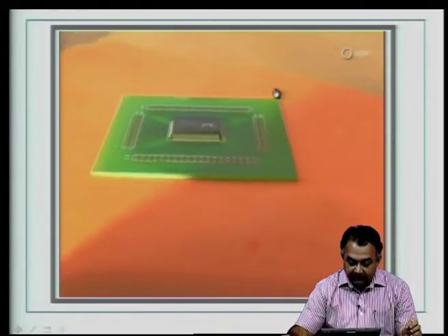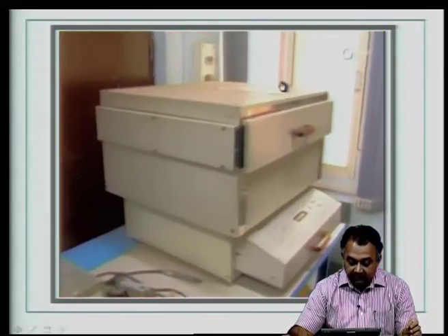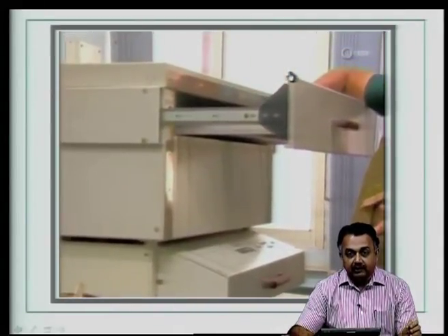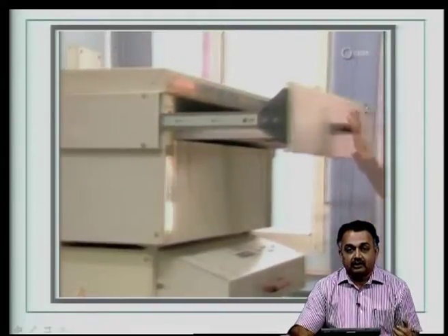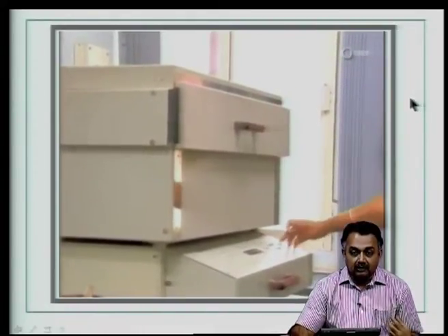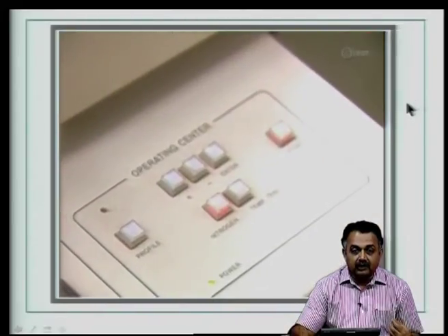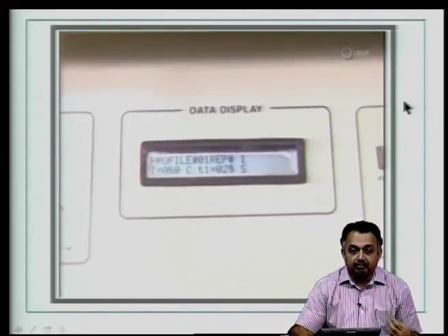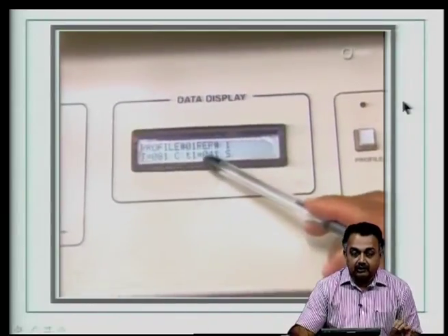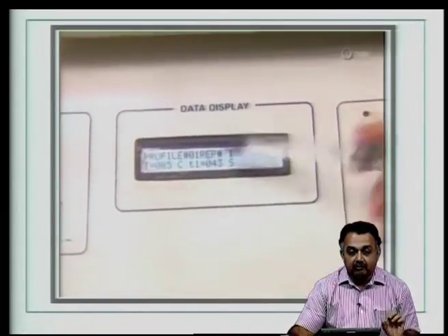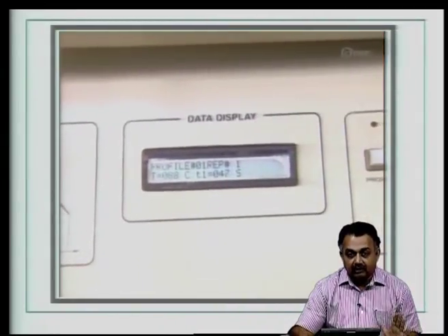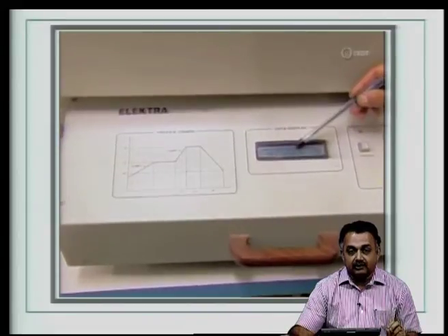So, once you are satisfied with the alignment process, again you take the board to the reflow, and then you expect due to surface tension the solder does not bridge. All the solder that is reflowed will get attached itself to the pins of the gull wing component, and making sure that the gap between pins, which is a dielectric, is completely devoid of the solder paste material because of the surface tension process.